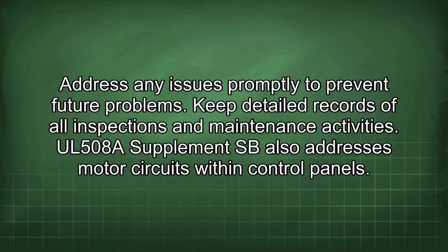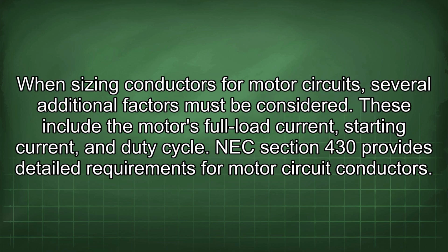UL508A Supplement SB also addresses motor circuits within control panels. When sizing conductors for motor circuits, several additional factors must be considered. These include the motor's full load current, starting current, and duty cycle. NEC Section 430 provides detailed requirements for motor circuit conductors.